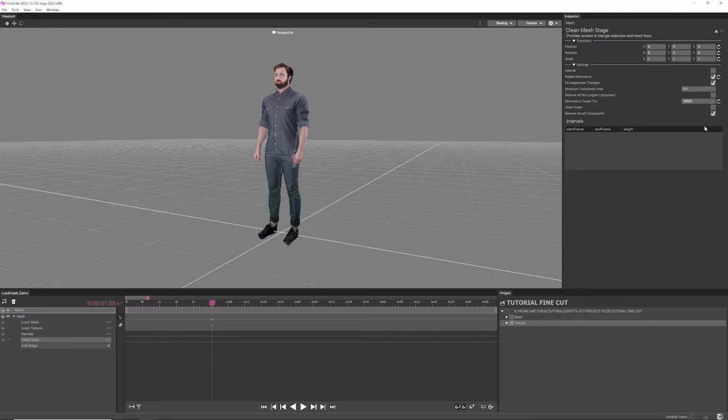Now, as you're processing, it's rare that one set of parameters will work for the entire clip, and it may take a few tries to figure out exactly what parameters are going to create the best results. With this in mind, we recommend selecting a small range of test frames over different points in your clip to begin figuring out what parameters are going to work best.